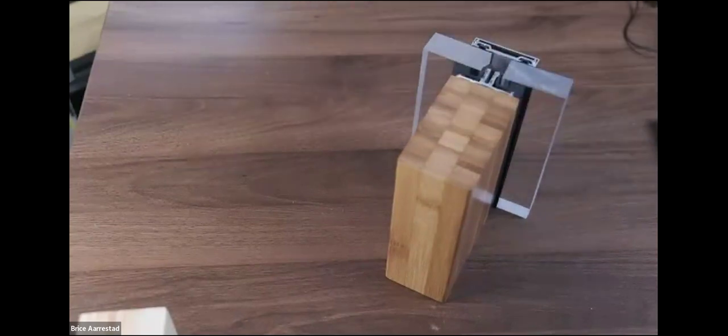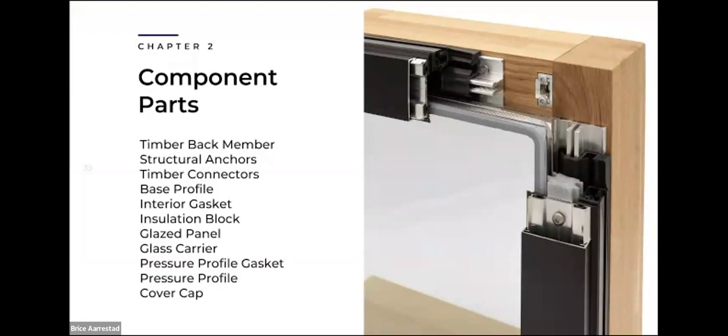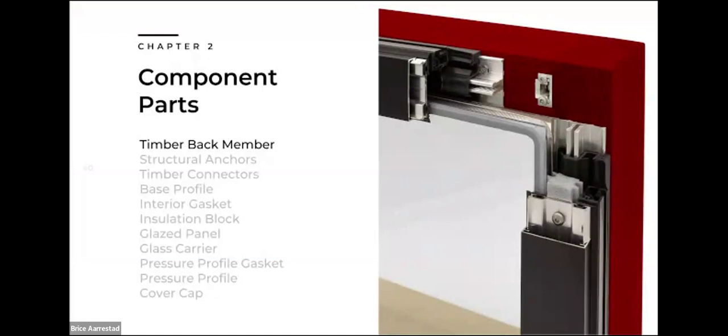When it comes to the glulam, the timber part, we can do a lot of different things with it. There's different wood species that we can use. Doug fir and southern yellow pine are some softwoods. We can do some hardwoods like white oak, maple, ash, all sorts of different species there. The sample that I'm showing you here is a bamboo, so laminated bamboo, like I showed on that Saugus project.